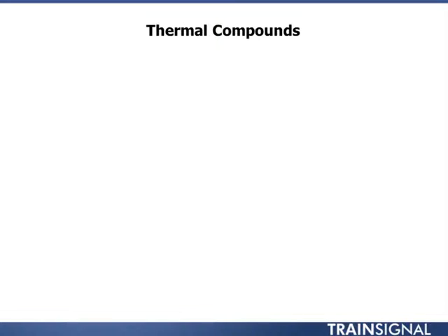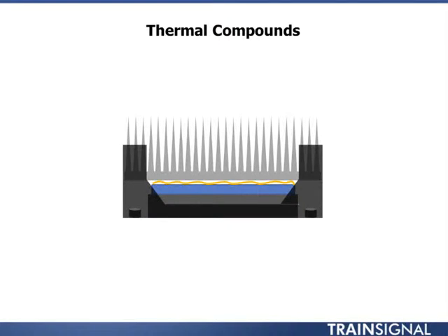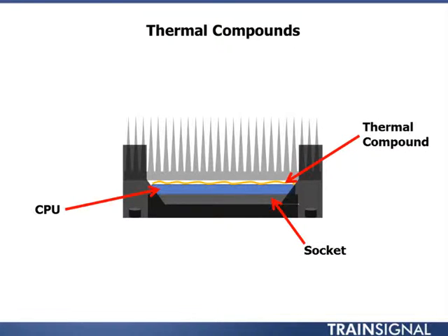Now sometimes, in fact almost always, a thermal compound is placed between the CPU and the heat sink. You actually see pictured here in assembly. You have the socket, which contains the CPU. You have the CPU itself, and the thermal compound. This actually promotes the transfer of heat from the processor to the heatsink assembly. Only a thin layer of compound is required. If you use too much, it can actually make the process work less efficiently. So here you actually see the heatsink bracket, the heatsink itself, which we looked at just a moment ago, and then the compounds we also talked about as well.